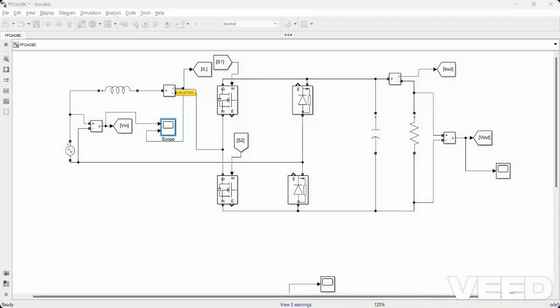Yep, so more or less that is the way you build it. You build a double PI loop and make sure that your electrical parameters are properly calculated, it's not going to be a hit and trial. It's a quick and dirty way to explain it, but you need to properly calculate.